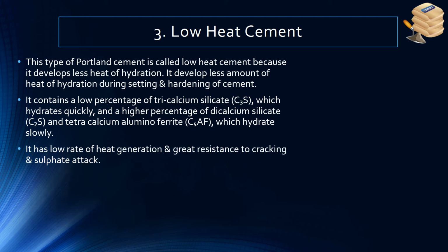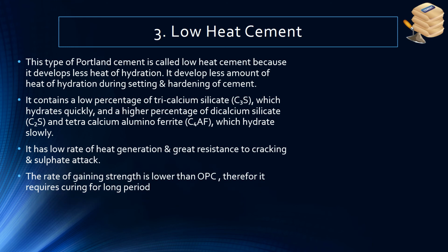It has a low rate of heat generation and great resistance to cracking and sulfate attack. The heat is developed in less amount so setting time is prolonged, therefore cracking is minimized. The rate of gaining strength is lower than OPC, therefore it requires curing for long period.